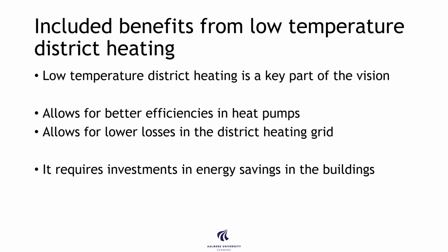So one of the first things, a key part, was to include low temperature district heating. This allowed us to have better efficiencies in heat pumps. It allowed us to lower the losses in the district heating grid. However, it required that we made investments and energy savings in buildings and in equipment in buildings.